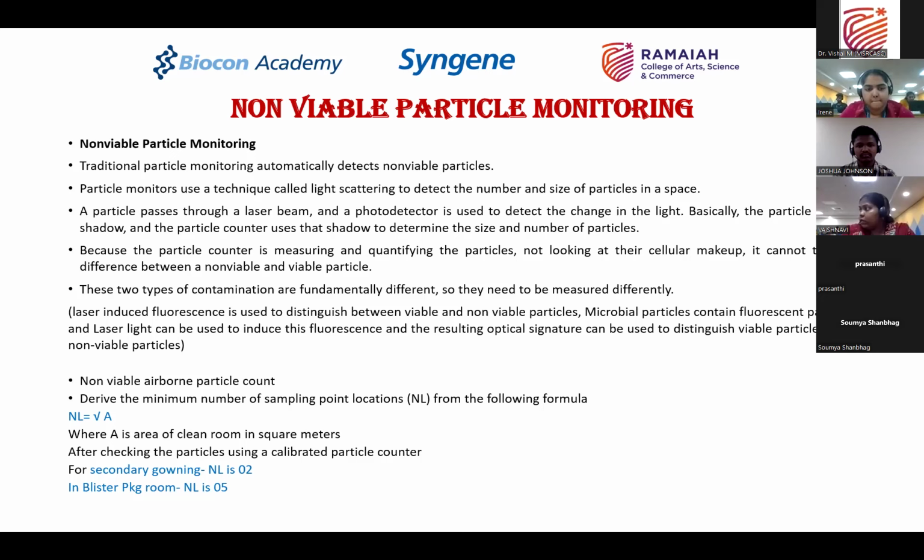When any dust particle passes through or comes in the path of the laser beam, there will be a change in the light, and the shadow of the particle will be created. From that shadow, the counter will detect the size and the number of particles.